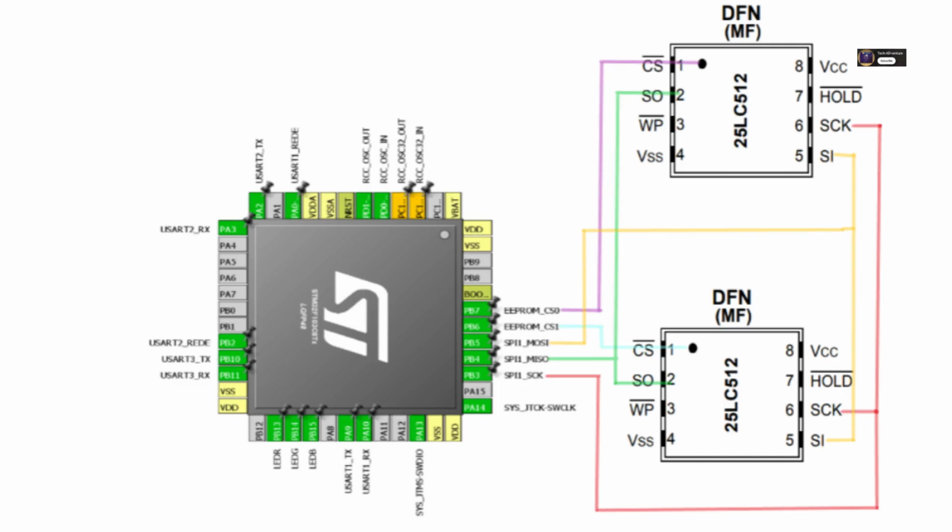Number 2 is not respecting page boundaries during programming. Writing past the end of a page and having it wrap around unexpectedly corrupts data. Forgetting to send the right enable command before every single program or erase operation. It's easy to forget, and the chip just silently ignores your command. Not polling the WIP bit after a program or erase. Sending the next command while the chip is still busy internally. Recipe for disaster. You need that polling loop with a timeout.